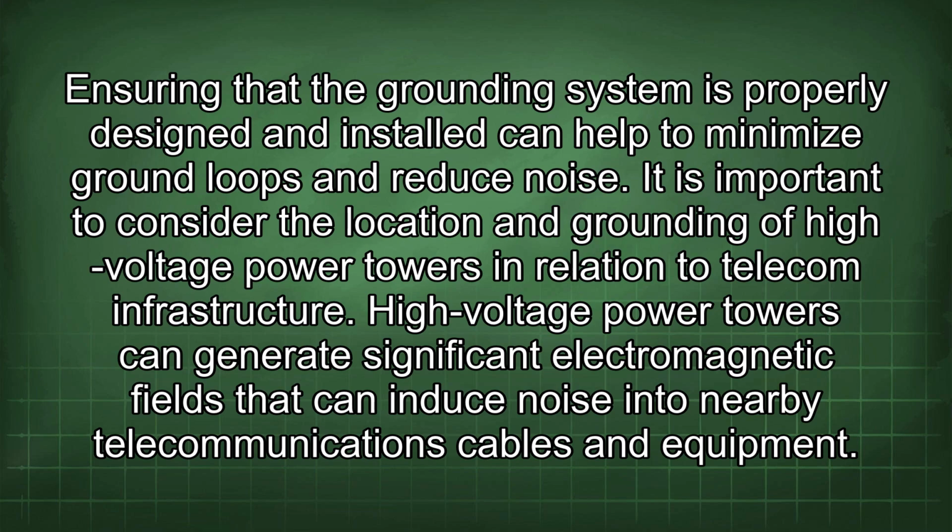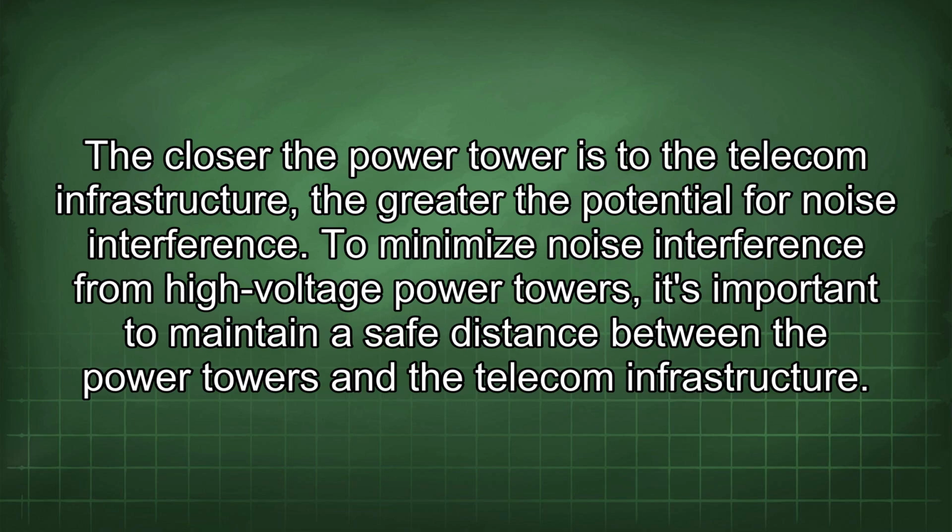It is important to consider the location and grounding of high-voltage power towers in relation to telecom infrastructure. High-voltage power towers can generate significant electromagnetic fields that can induce noise into nearby telecommunications cables and equipment. The closer the power tower is to the telecom infrastructure, the greater the potential for noise interference.